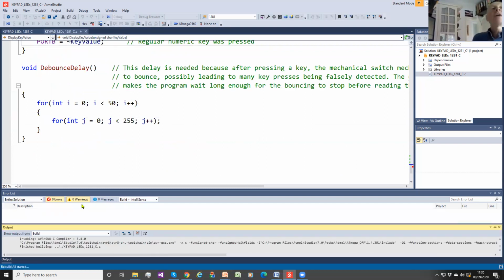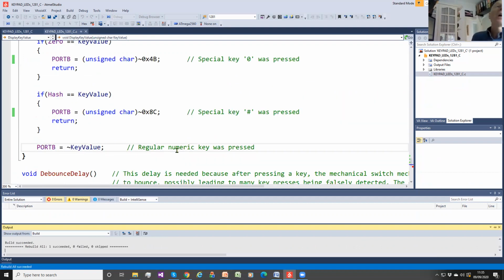0 warnings, you see, because I've told it that's now only 8 bits. Unsigned char, as I said earlier, is forcing it to treat it as 8 bits. So the compiler knows that's 8 bits, that's 8 bits, no problem. This is the difference between being a beginner not knowing what's going on, and being someone with a lot of experience. And you can only get that experience by doing it yourselves. Obviously, my role is to put it in front of you and say, hey, look at this. But you as students must get the habit of doing this by experience.